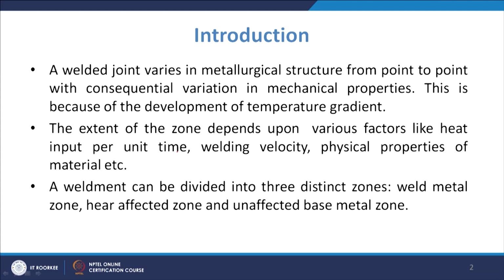Now, the extent of this zone will depend upon various factors like heat input per unit time, the welding velocity, and the physical properties of the material like the thermal conductivity, or thermal diffusivity in true sense you can say. Then you have the melting point. So, all these things determine the width, or the dimension, of that particular zone.